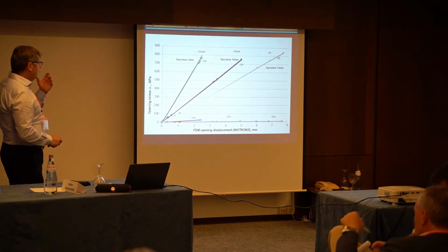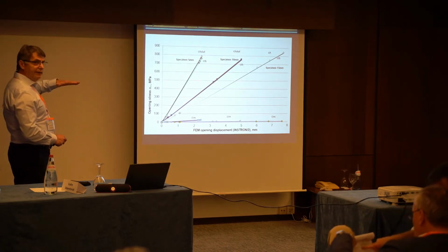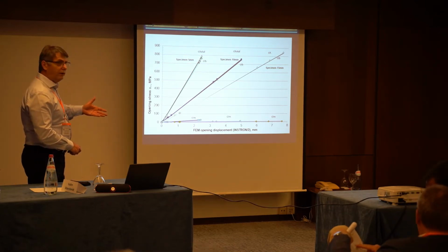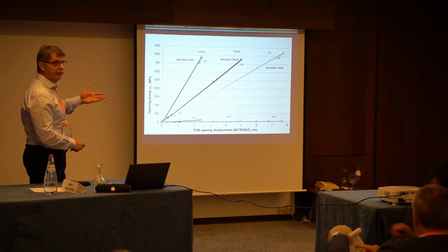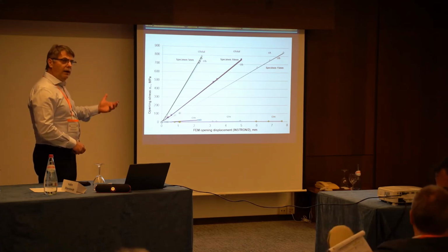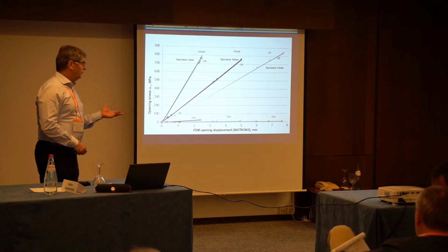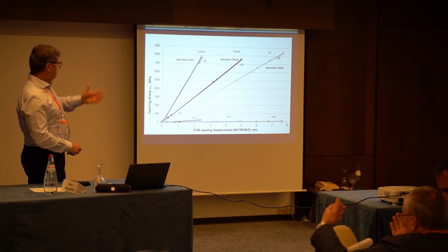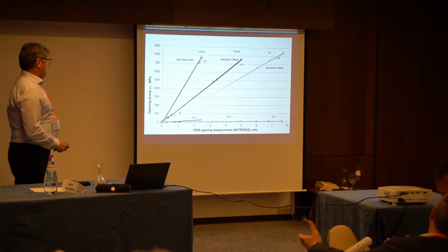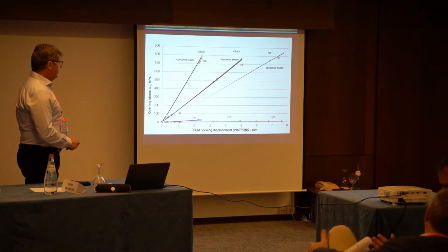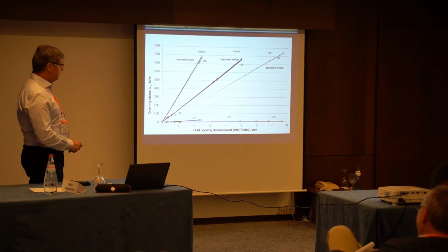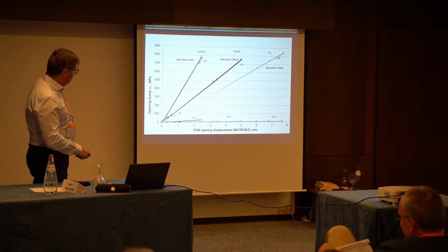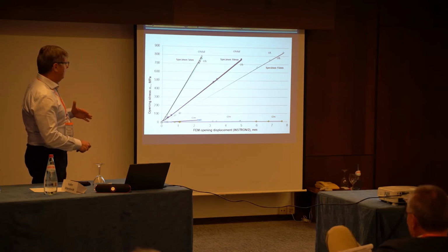So it means that you get about 800 megapascals, but you can say that the tensile load has lower influence than bending. And this is really the reason why, when you establish the model, which I will show you later, you just concentrate on the bending and how the bending behaves. So here we did the same for 5 millimeters, and for 10, of course, the specimen is more closed in bending, so you have more displacement for the same load level.